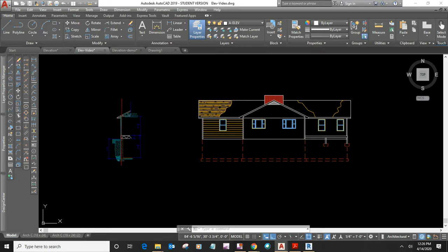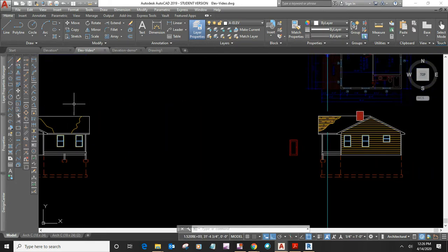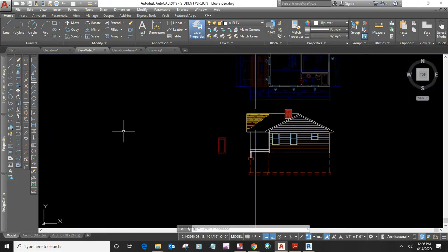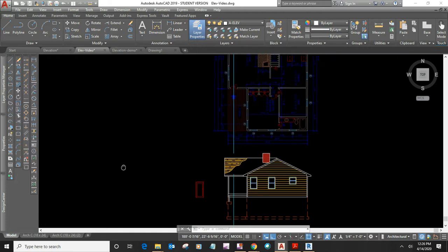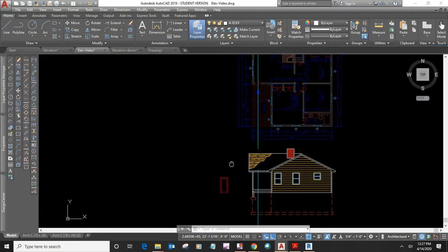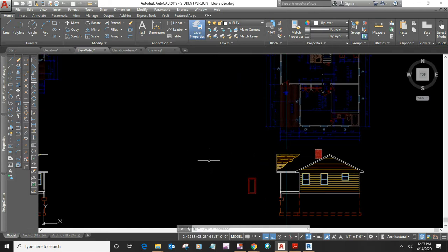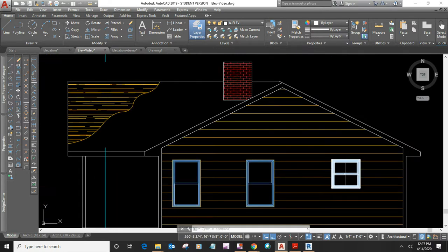Before I jump into the hatching, here's kind of what your side view is going to look like. I went into how to copy these X references over, rotate them and project them down. You're using the same elevations from the front view as far as the heights. That window there, I copied it from the window file and pasted it in here.